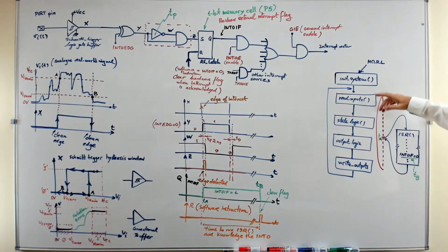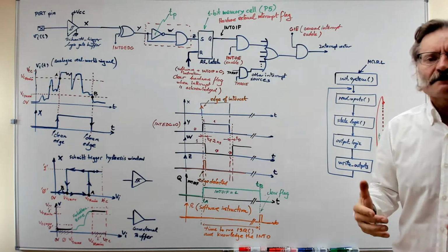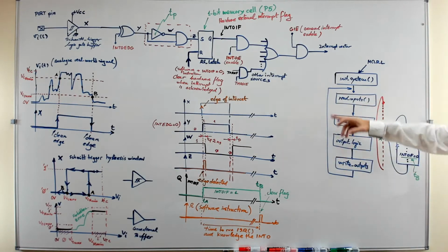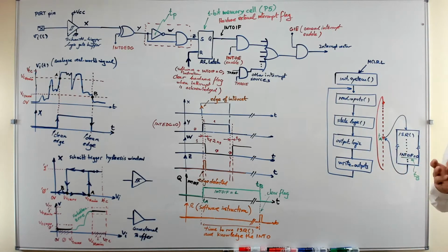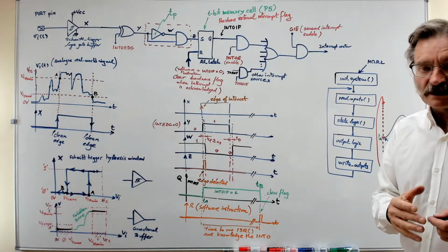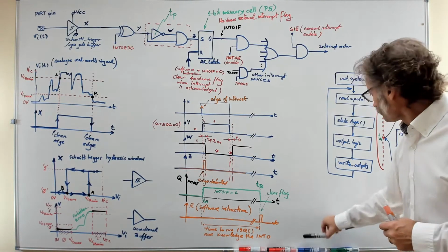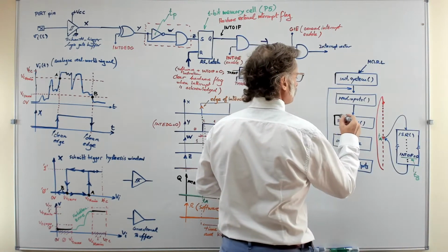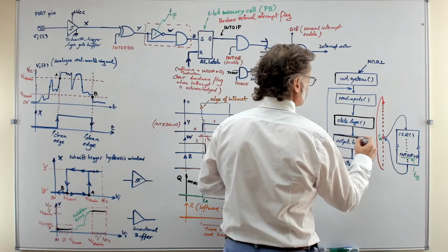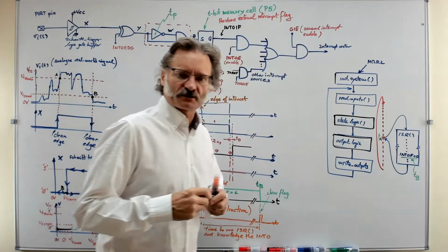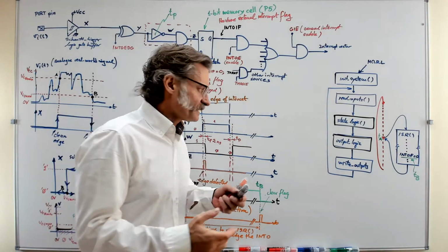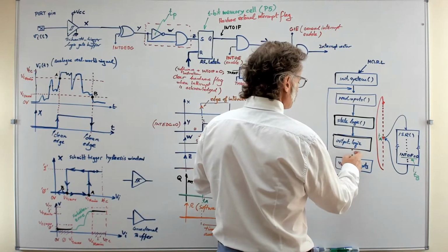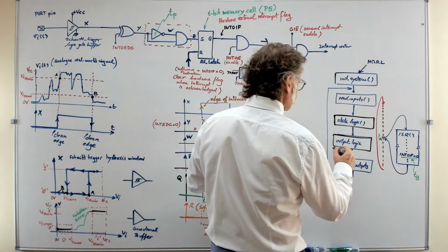Okay, so this is the main program, as you know very well. For example, initialize the system and then poll the inputs that are not interrupts, just poll inputs whose signal level you like to know in this loop. Then perhaps if you are running a finite state machine, which is our case, what you have in mind is to run software functions, the state logic function and the output logic function. And perhaps why not, because you have something else for processing information, you like to operate here, who knows, the data path. That is the main loop, okay?